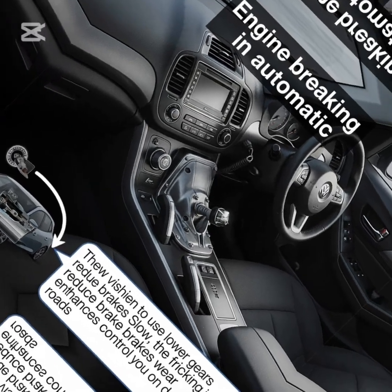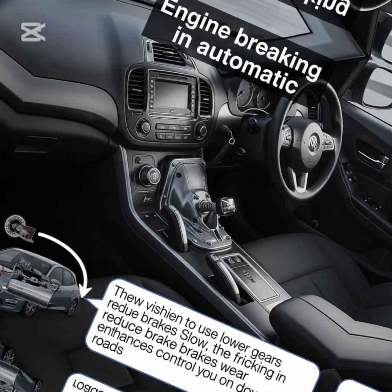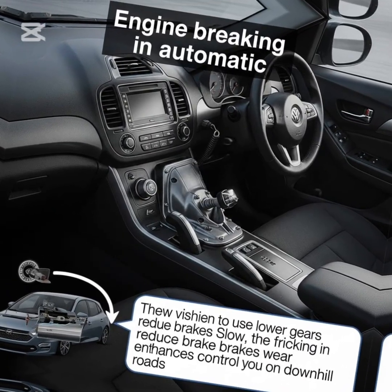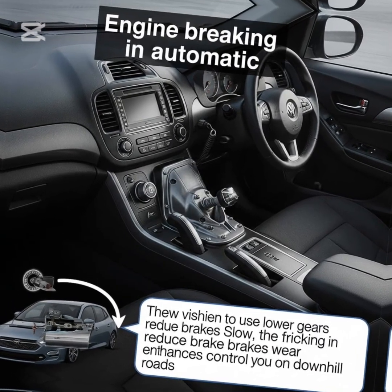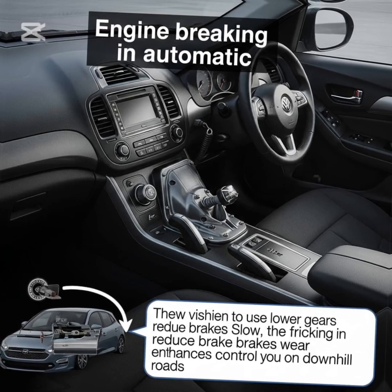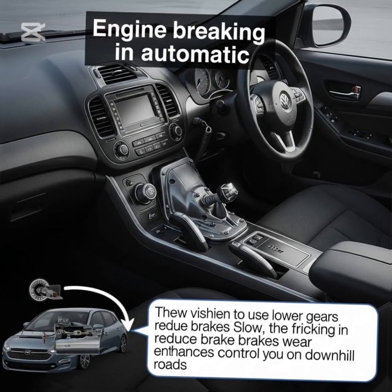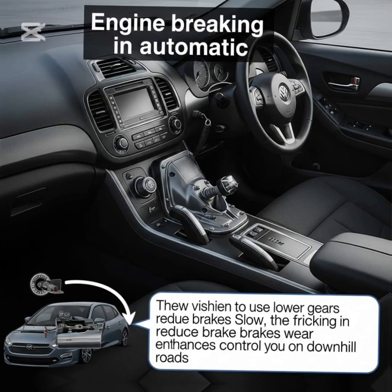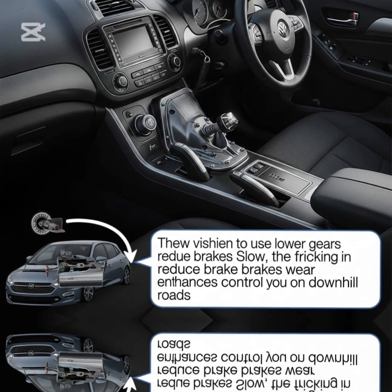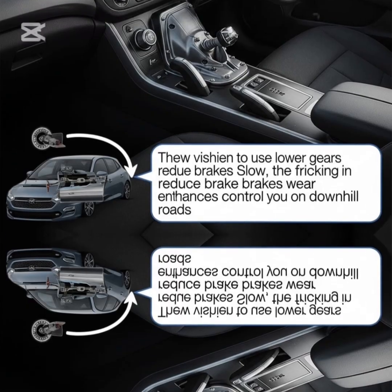Chapter 6. Engine braking in automatic cars. Engine braking occurs when the engine slows down the vehicle without using the brake pedal. In automatic cars, engine braking is achieved by selecting lower gears or reducing accelerator input. When descending hills, relying only on brakes can cause brake fade. Using engine braking helps maintain controlled speed while reducing brake wear.